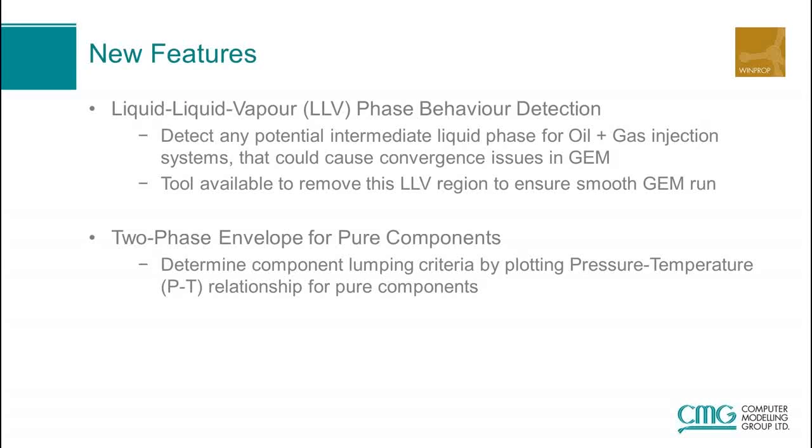We also have two-phase envelope creation for pure components. Previously, if you wanted to do a two-phase envelope, you had to look at pseudoization of components or lumping. Now you can do it for pure components, being able to plot that pressure-temperature relationship.